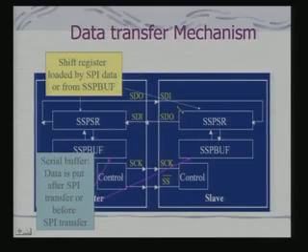With regard to the device or the slave, I have also shown similar registers. Whether they are named SSPSR or SSP buff or not, they will have similar capability. I have to have a serial shift register to get the data, and from there it has to be loaded in parallel to a buffer register, and vice versa for the purpose of transmission. So, what we have seen so far are mechanisms for connecting peripheral devices to the processor using a serial bus.